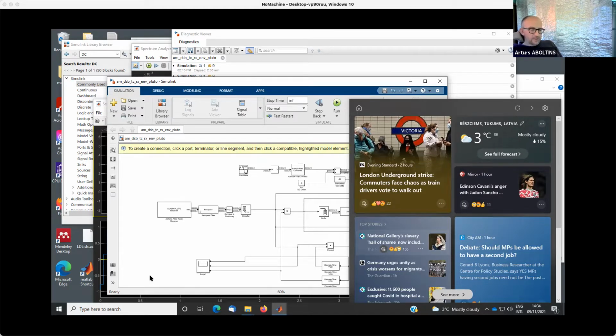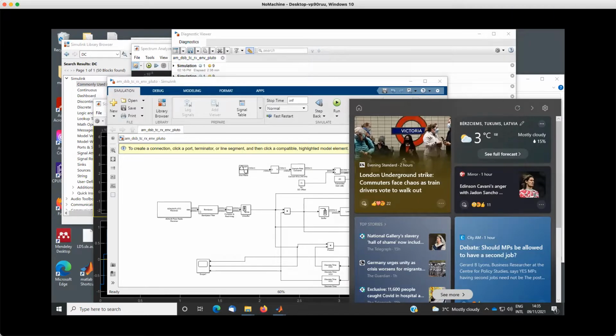So you can use also, because in this place we have this discrete time derivative connected to this first VCO, and then it goes out. So instead of this scheme, you can use this scheme with the second VCO, but you can also not use the second VCO, and connect this derivative at the output of the first, because this derivative does approximately the same as the second VCO, but at much lower computational cost. But last time we discovered that quality is not that nice in this case.